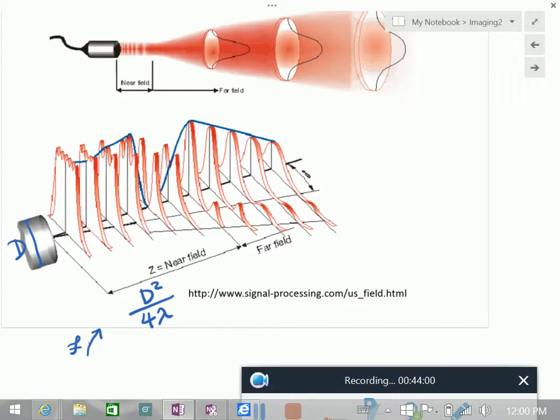So you don't want to make any attenuation measurement, anything which has to do with amplitude measurement, in the near field. Absolutely not, because it's unreliable. You exclude the part of the signal that's from the near field. We can calculate it very easily. So this gives you what? The Z. That distance. Right.